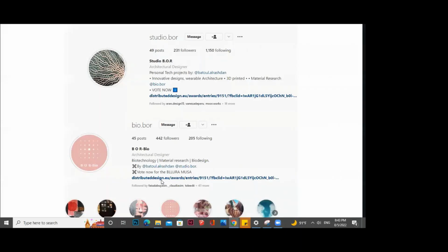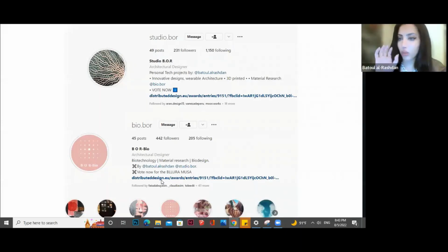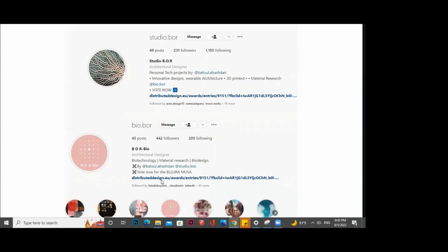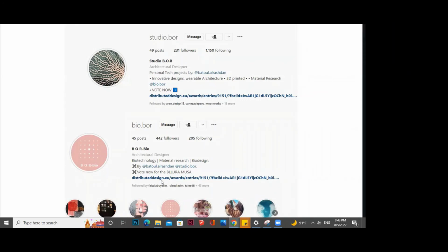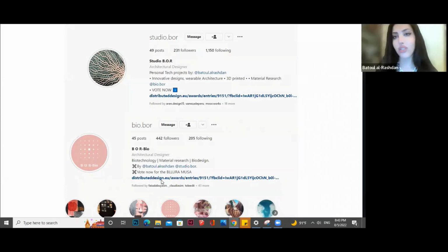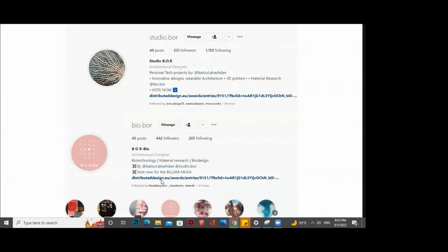But the normal design is okay, so you end up with your 3D design on a software, and then you export from that design software as STL. Then you put it into a slicing software. I use Cura. It depends on the printer. Cura is related to Ultimaker and some other printers. Okay, makes sense. So you design, export 3D, put it in the software, then you adjust the parameters according to the machine and the materials, and then you go ahead and print.